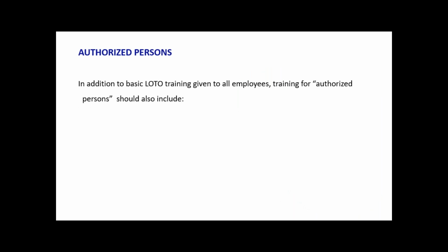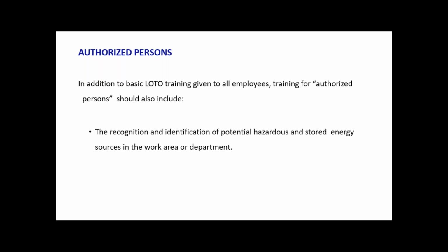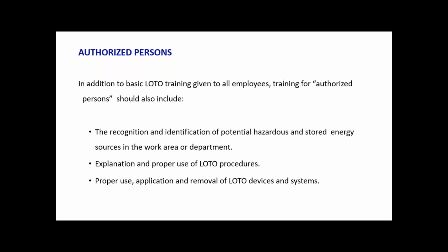So authorized persons, we have already discussed about this person, that he should go through the different types of LOTO trainings, and he should recognize and identify the potential hazards and the stored energy sources in that work area or department, and then he can explain the proper use of these LOTO procedures to the remaining employees in that area or department.